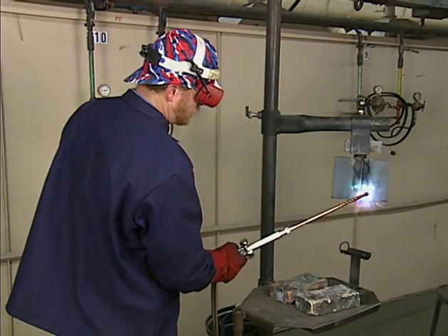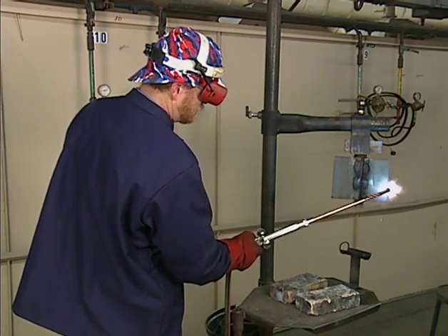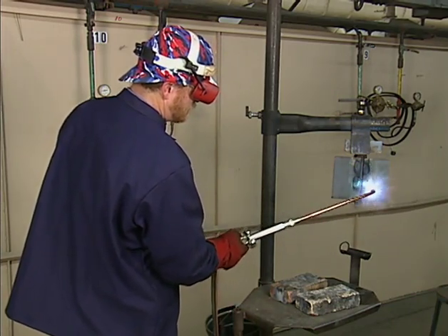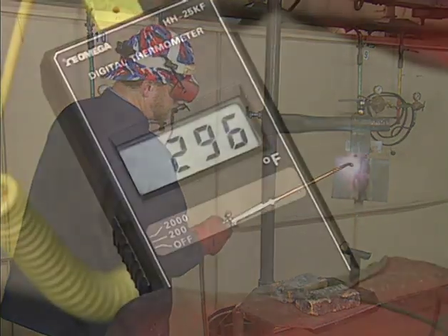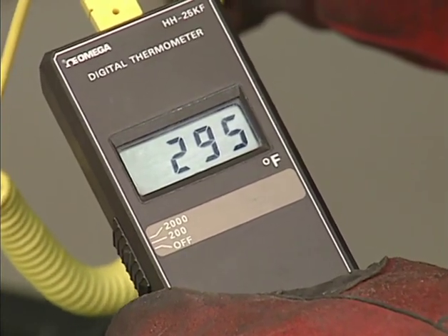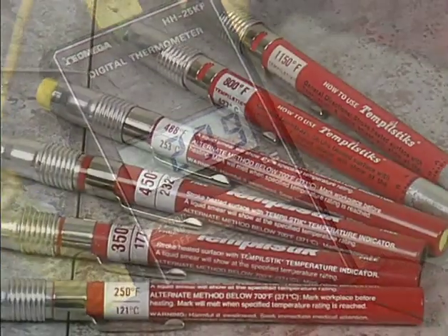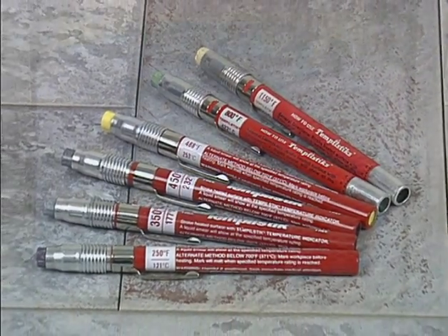But when you preheat the base metal, the heat of welding has no place to go, so it stays in the weld, allowing it to cool more slowly, which reduces the chances of forming martensite. On some metals, you have to maintain proper interpass temperatures. You can use a pyrometer or heat-sensing crayons to monitor temperature throughout the welding operation.